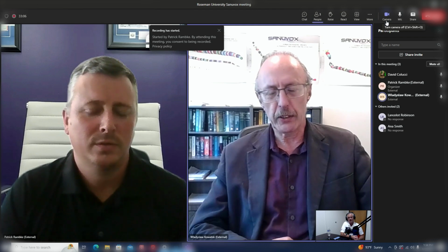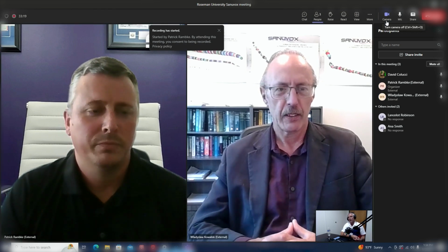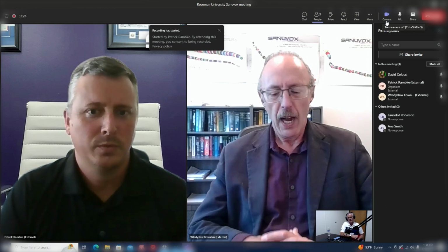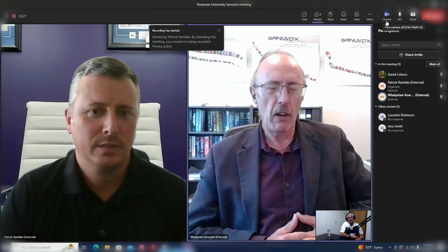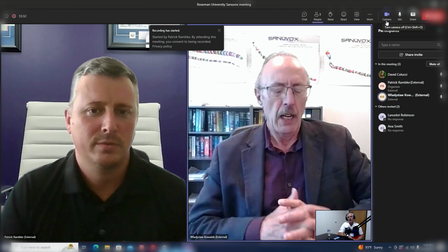Yeah. So, and then the lifespan of those lamps, how long do they last? Oh, yeah. UVC lamps, medium pressure and low pressure lamps, will typically last about 10,000 hours, which means a once a year change out. Okay. The LEDs, I can't tell you anything about, but the far UV lamps are rated for 4,000 hours, which means you might have to change it twice a year. Okay. And then a placement within your HVAC, is there a specific spot that you put those? Ideally, the lamp would go in a long stretch of ductwork, because the longer the ductwork, the more exposure time you get. Okay.